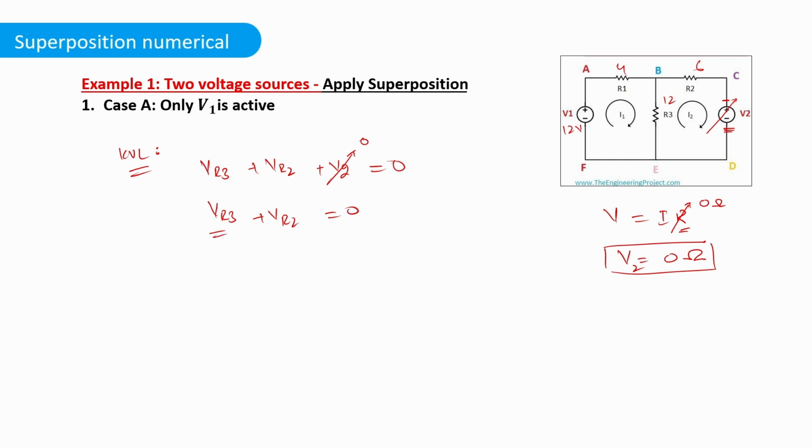Now, voltage across third resistance. Once again, take notes of this. This R3 is actually shared between both loops. So the Ohm law will actually become I1 minus I2 or I2 minus I1. Remember that since we are applying the KVL in the second loop, this time this will become I2 minus I1. This is a standard method, okay? When you are solving a KVL in a particular loop, that current will be written first and then minus the second one.